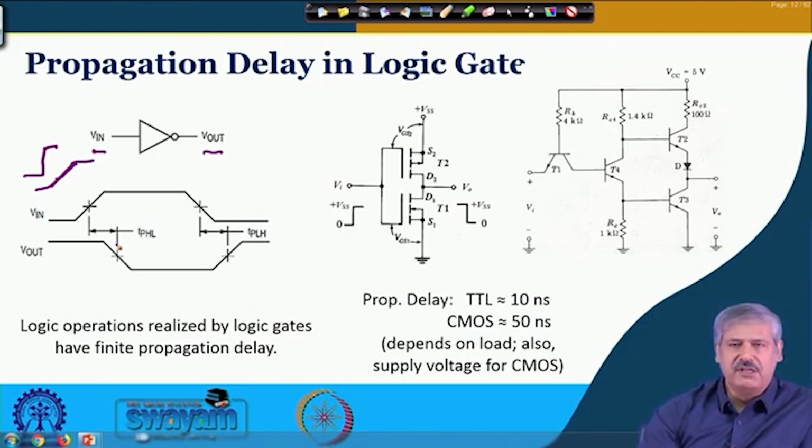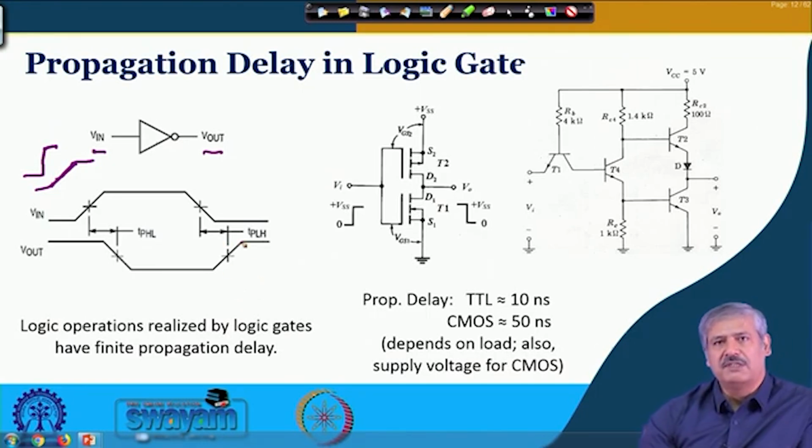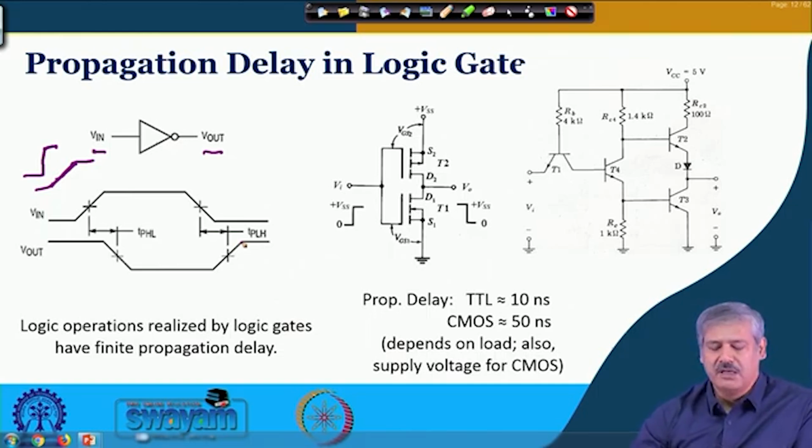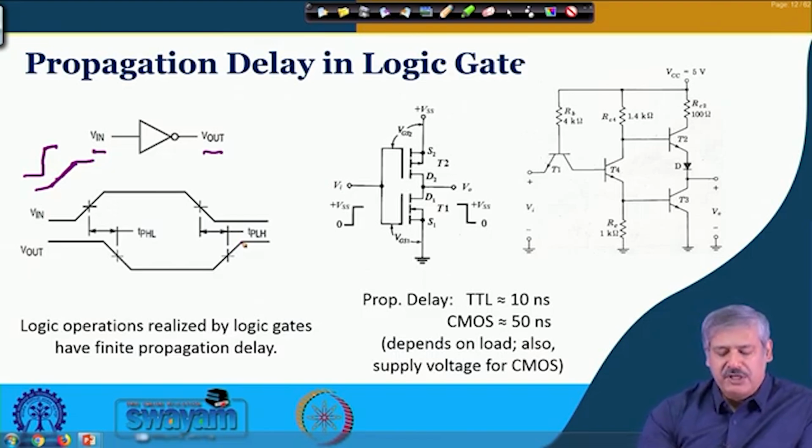This is the propagation delay at the output going high to low, and similarly the opposite is low to high: the input is at the 50% level going from high to low, and the output goes from low to high when it reaches the 50% level. So, this is the propagation delay at the output, low to high. Usually they will be a little different from one another, because in CMOS there is a load capacitance, as we noted before.